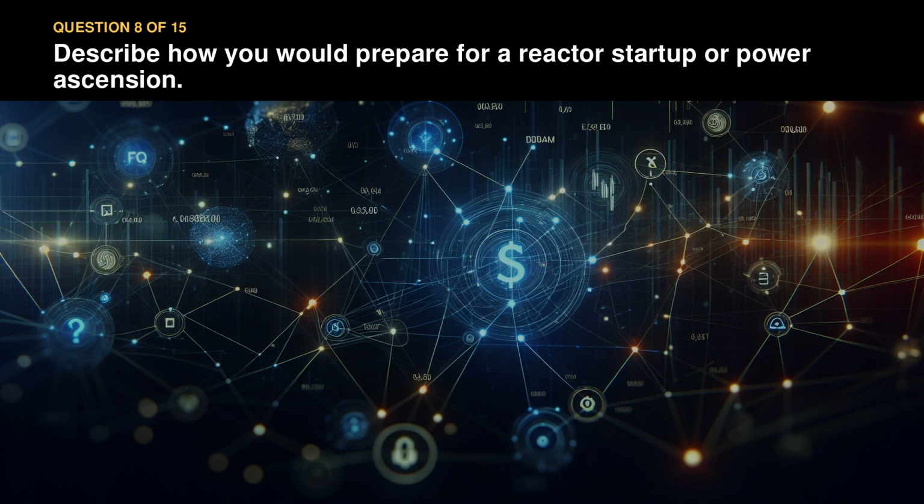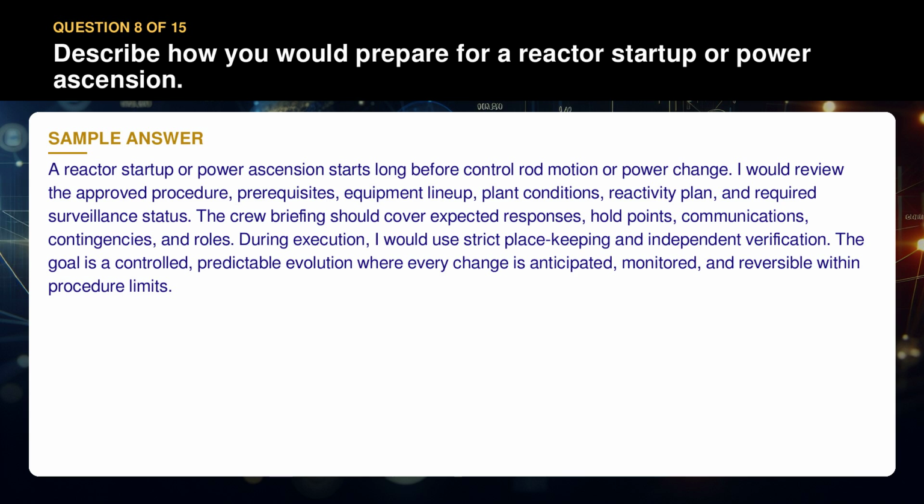Question 8. Describe how you would prepare for a reactor startup or power ascension. A reactor startup or power ascension starts long before control rod motion or power change. I would review the approved procedure, prerequisites, equipment lineup, plant conditions, reactivity plan, and required surveillance status.